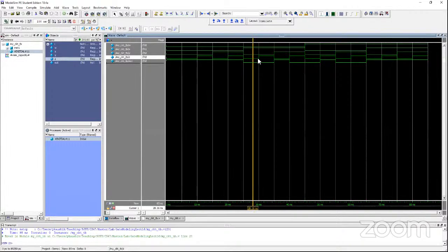So logically it is toggling. And we are seeing that the MSB, most significant bit, is changing once. That is expected. The most significant bit in that sequence will change once. So at this point, WXYZ represents 0, and I expect my output to be 1, right? So it is happening there.